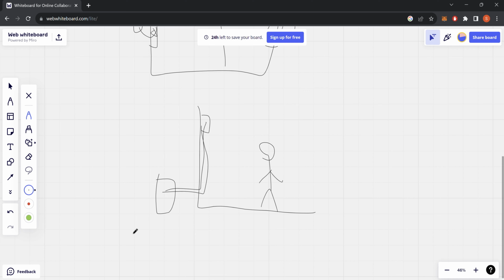So what's happening is the ductless units are designed to just mix the airflow that's already in the room, but do all the same processes. So instead of having one central fan that's moving all the air in the house, you have a bunch of individual units that are just cycling air in their one spot. So it's going to suck in air either from the top or from the bottom, and it's going to blow that air out into the room. So the process of the heat exchange is still happening inside this unit, but the air is only coming from the room and going back out into the room. You're not able to pull fresh air in the same way you would for a central system.